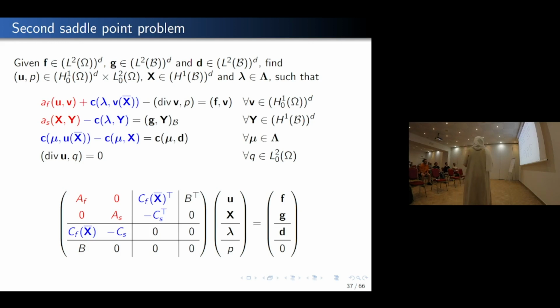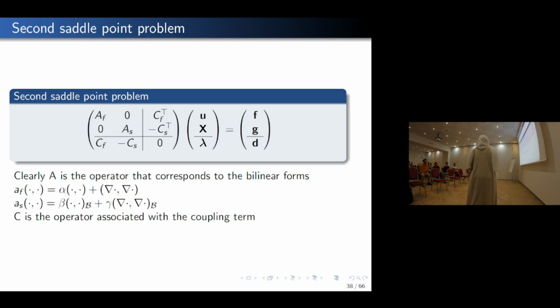So in order to find a good discretization for our big FSI problem, we will break it into some pieces, and we will take this small piece in here, this part, aside, study it, find the stable finite elements for that one, and then use it for the big problem. So this is what we will do. So we will look deeper into the upper left block.